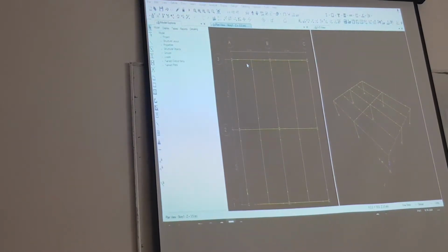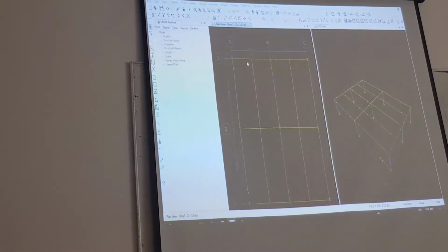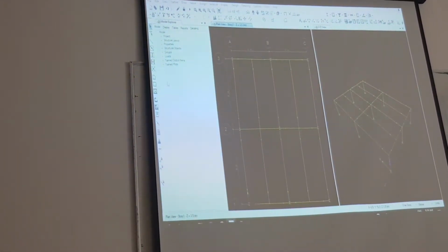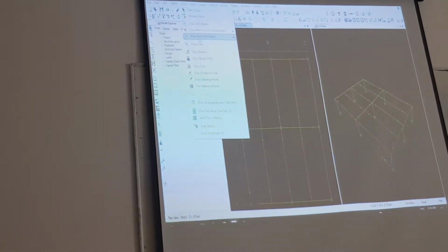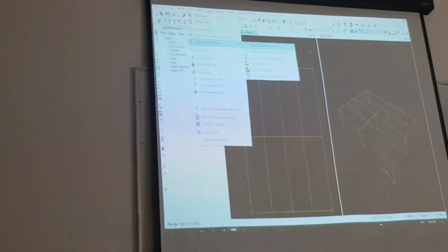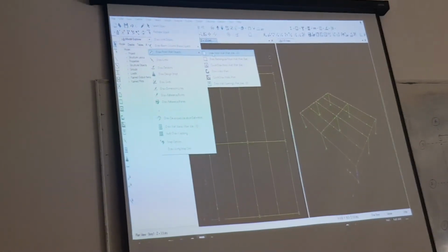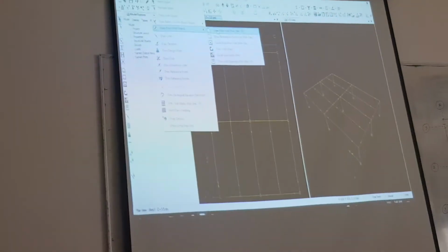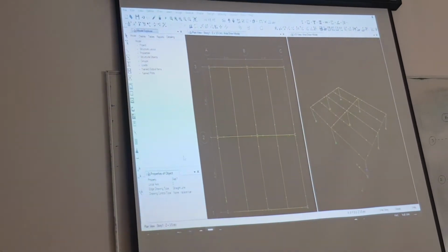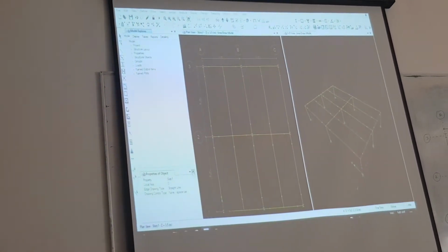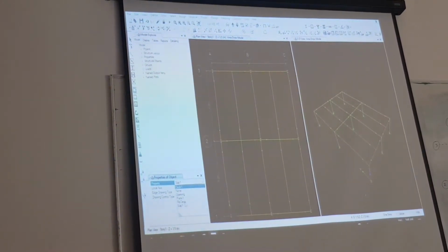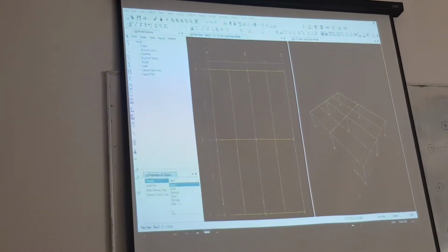Okay. Now after defining all the secondary beams and the primary beams and the columns, we have to define what? The slab system. So again you have to go to draw. Then you have to click the first option called draw floor / wall. Click on this option. And in this window, make sure you select the one you have defined by yourself. As you remember, we have defined by the name called rib deck. So click on rib deck.